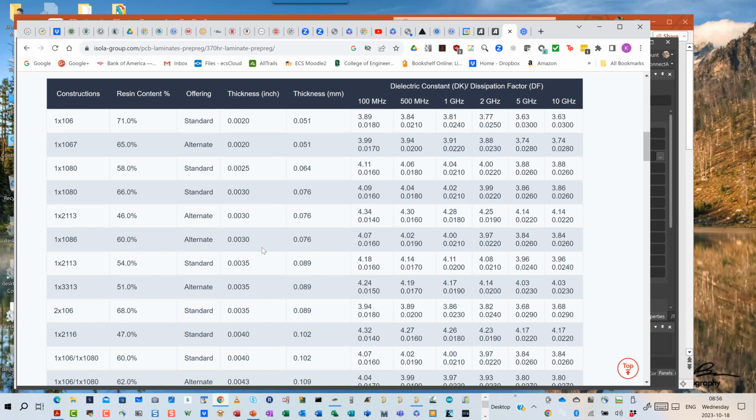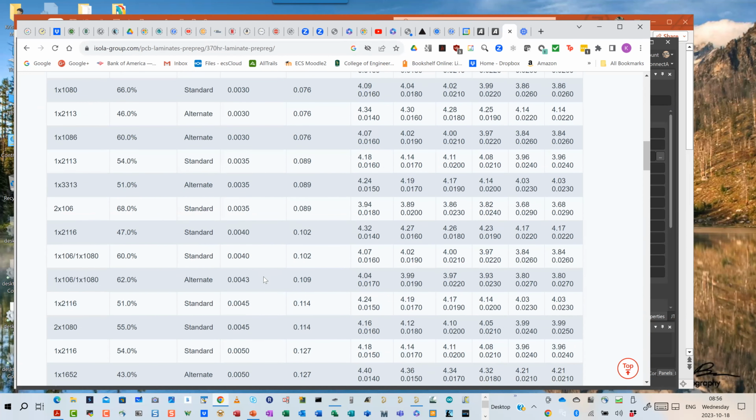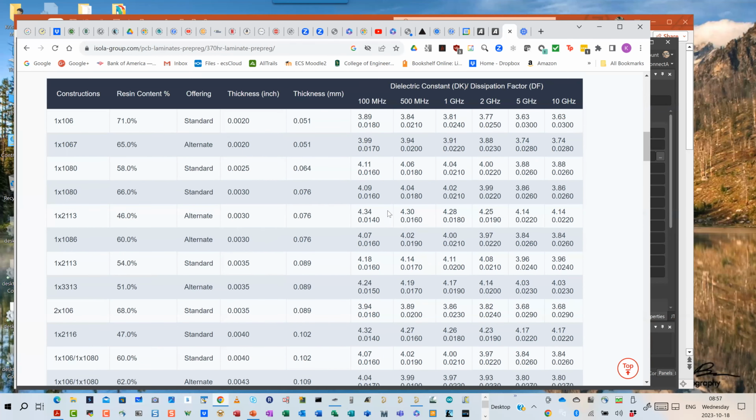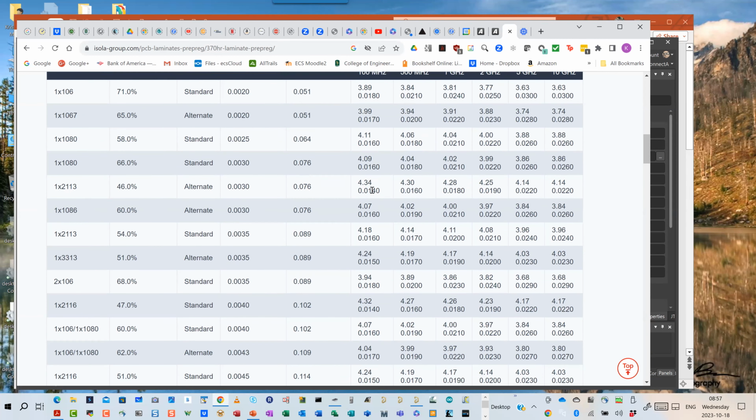I'm going to look at them based off of what the thickness I want is right here. So maybe like a 5 mil core, that one sheet of 2116. That one I probably could have looked at and left at the 4.1. But for all the others, the thinner layers there, the 3, 4 and 5 mil cores, right over here, we can see that I'm in like the 3.5. If I'm at the 2 sheets of 106 construction, I'm in that 3.8, 3.9 range right here.